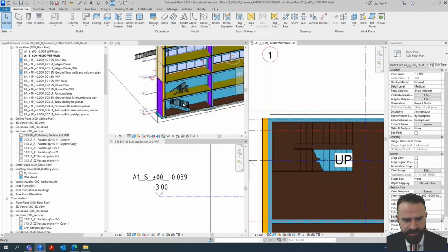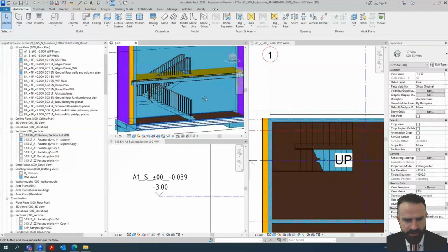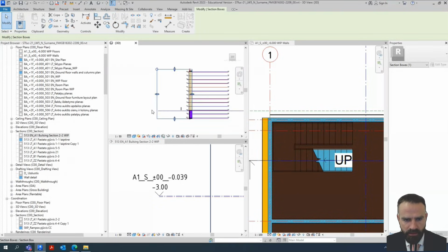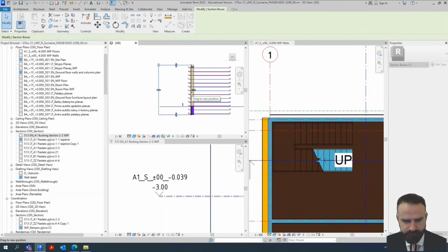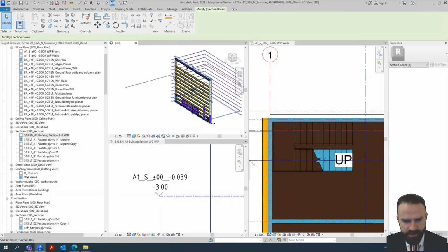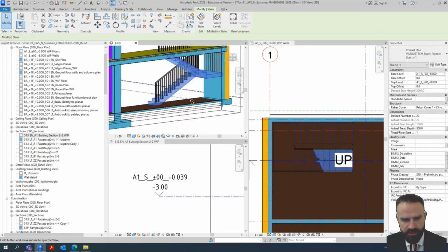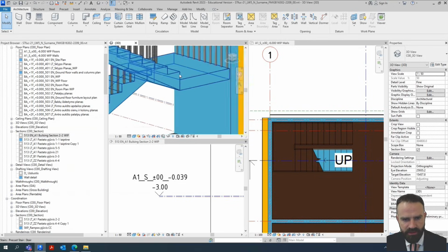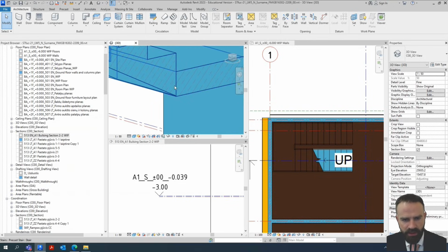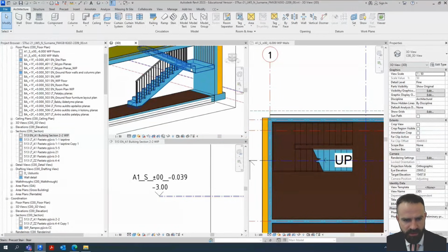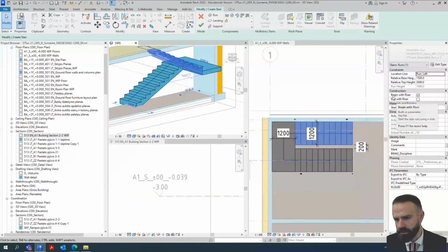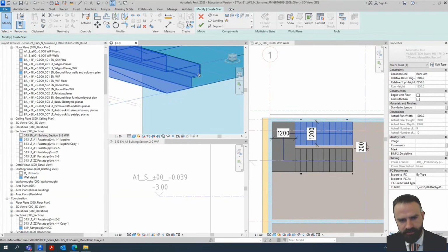and automatically the railings were added to my stairs. So now you can see all the stairs. So now I will use additional modification of my stairs and check out how the stairs look from the other side. From this side, I see my stairs run is connected to the landing not correctly because I don't have a notch. So it means I activate the stairs by double tapping, select this run, and uncheck the mark begin with rise. I uncheck the mark, and now I have nice notch here.